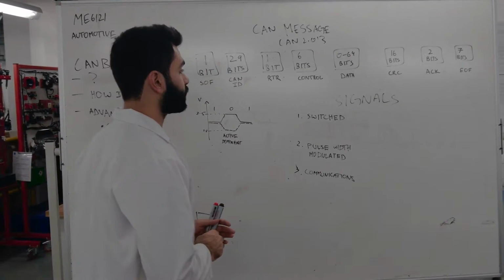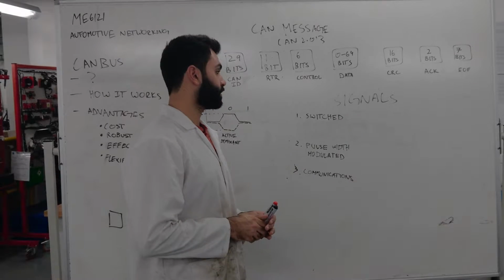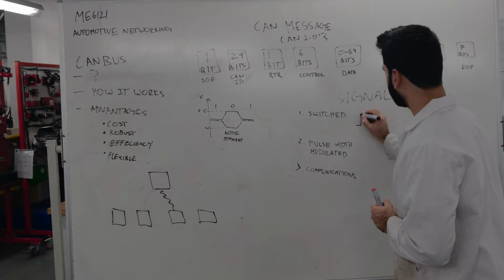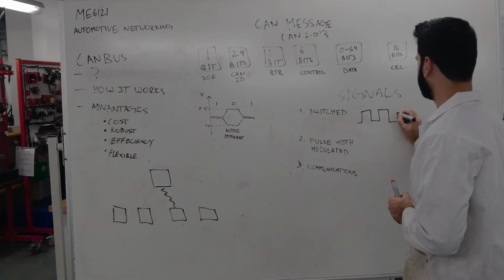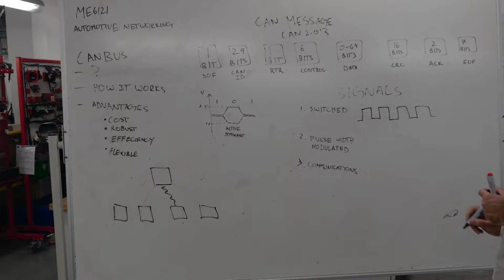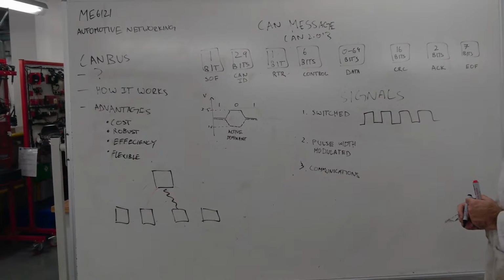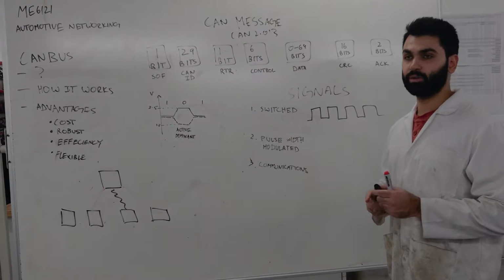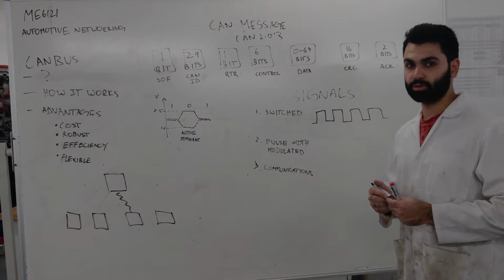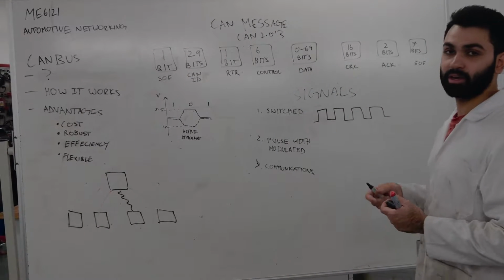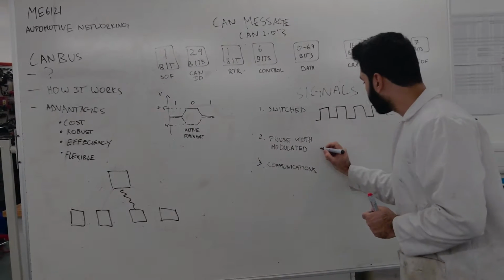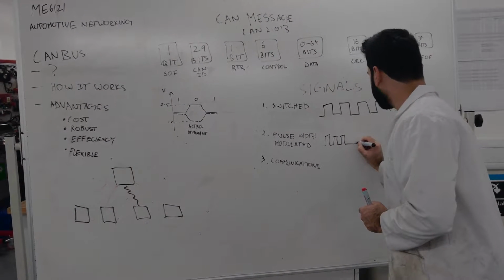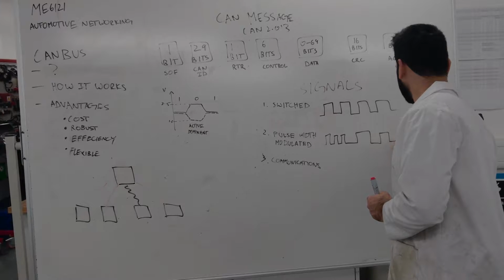Most outputs work electronically in 3 ways. We have a switch signal, which goes from on and off. We have pulse width modulated, which allows a device such as a motor to be operated at variable speeds by changing the amount of time electrical power is supplied to the device. That looks more like narrow signals or wider ones.